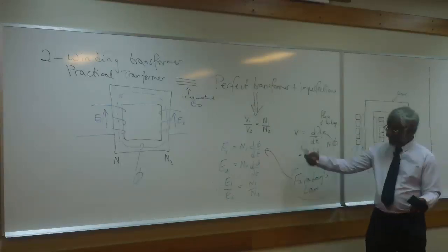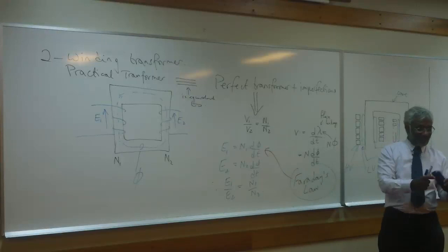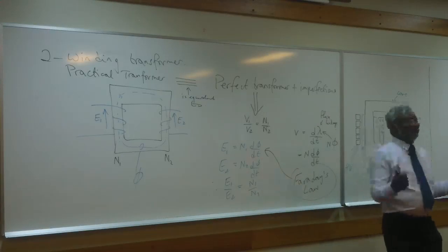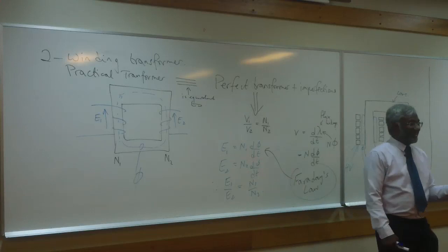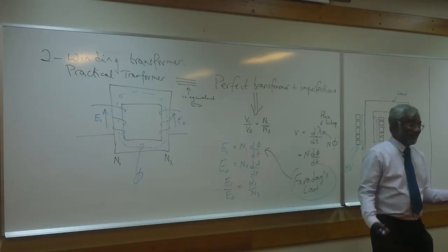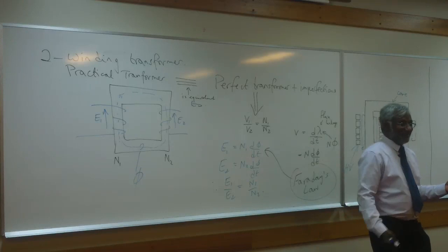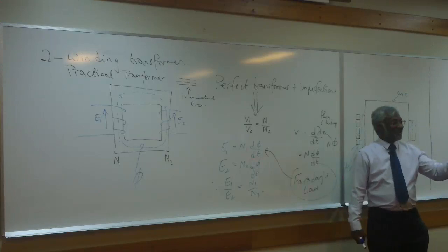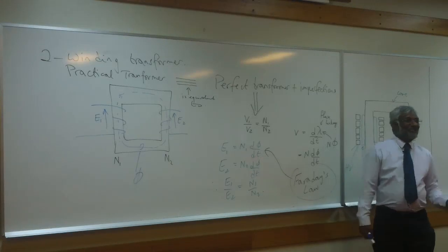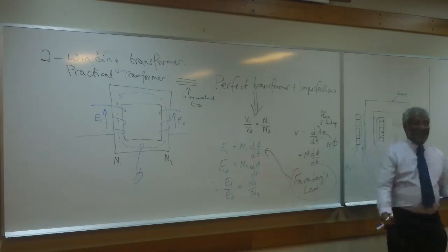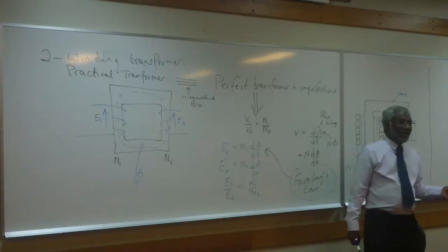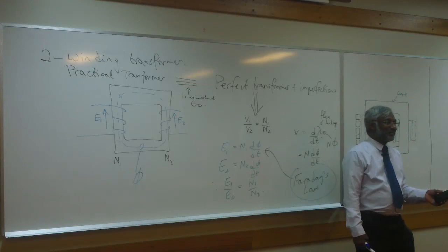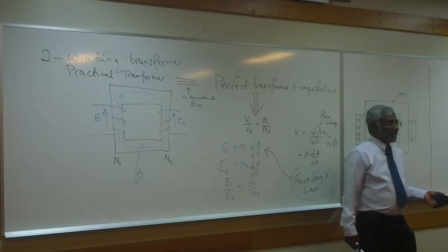I think, oh, I can get this little thing and I'll put 10 volts in and I'll get 1,000 volts out. Very happy. And I'm thinking I'm creating something I can get money for. But you quickly come back to earth when you realize that you might be stepping up voltage, but what are you doing to current? You're stepping it down by the same amount.